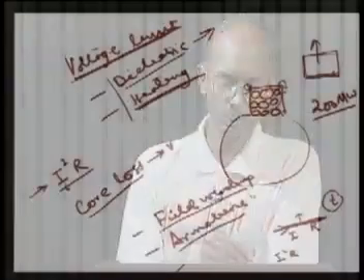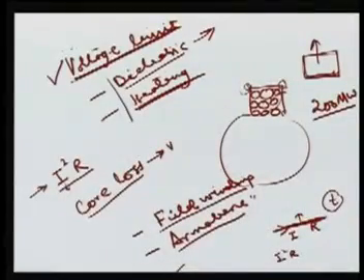To recap, we have seen two limits: the voltage limit and the steady state limit of the alternators. We saw two types of alternators: one is the synchronous wound rotor, another is the salient pole type. Salient pole generators are used for hydropower generators, where we rotate them at lower speed, because hydro turbines are efficient at low speed.